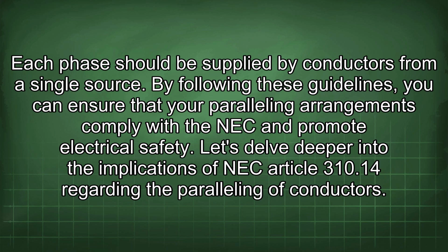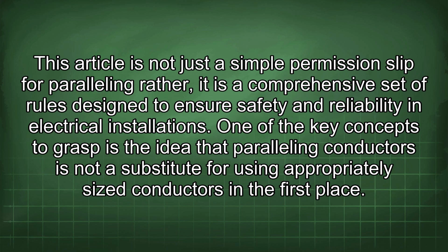Let's delve deeper into the implications of NEC Article 310.14 regarding the paralleling of conductors. This article is not just a simple permission slip for paralleling, rather, it is a comprehensive set of rules designed to ensure safety and reliability in electrical installations. One of the key concepts to grasp is the idea that paralleling conductors is not a substitute for using appropriately sized conductors in the first place.